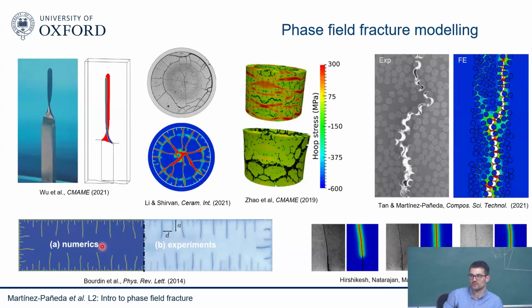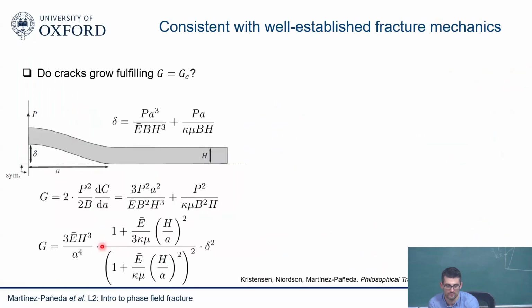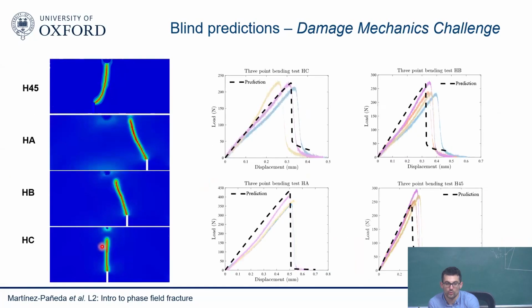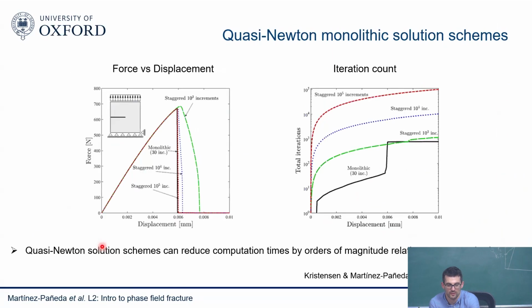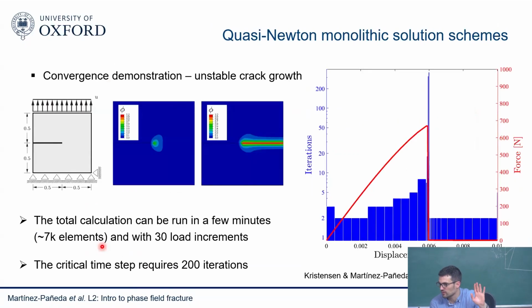For the monolithic scheme, in the BFGS, what is the influence of the tolerance values? Is there any significant influence? We use what comes in Abaqus by default. So you don't have to do anything about that. You're welcome to play with those things if you want, but you don't have to do anything special from your standard finite elements. It's fine.